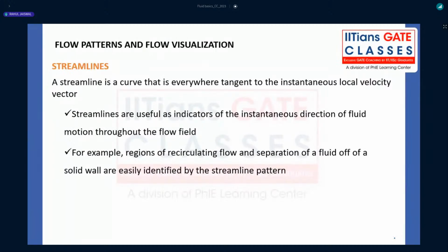For a simple 2D problem, not the 3D flow, you will be plotting the pressure field and velocity field. The moment we say field, that means a control volume, that means Eulerian description. That is a very fundamental thing. When you go for any MTech interview, whether or not you mention aerodynamics, they will ask this question: as an aerospace engineer, what will you be plotting as results? The pressure field and the velocity field.